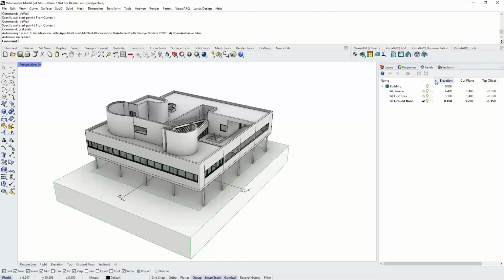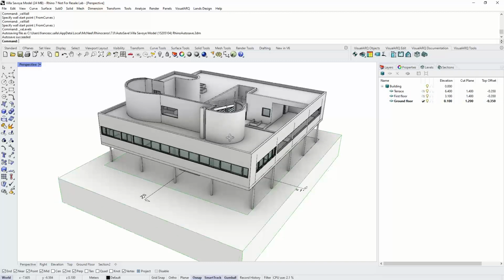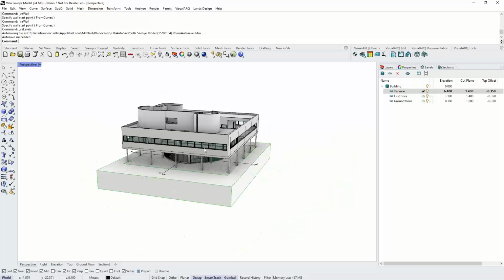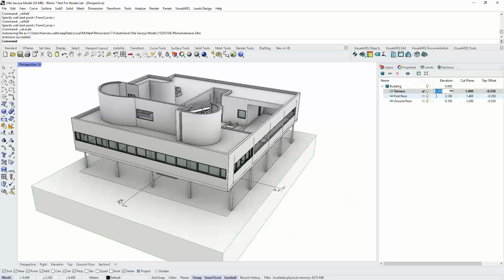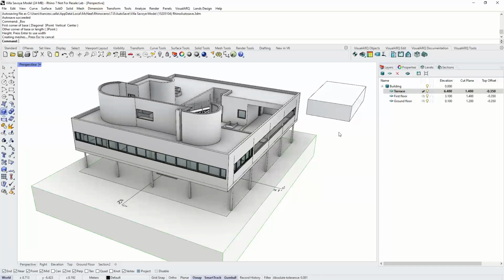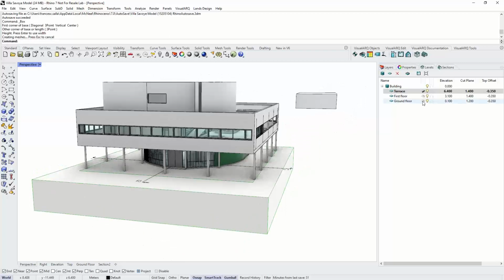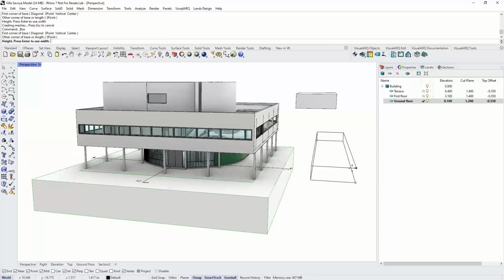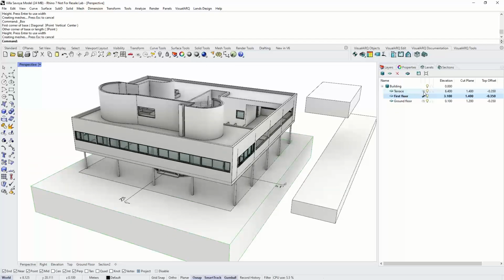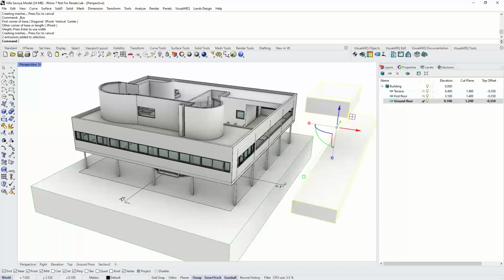And we have seen already how it works, but just to check it again in this last demo. In this project, we've got 3 levels. And basically from here, we can very quickly change the position of the construction plane, okay, that is located in that elevation. That means that if I draw anything now, this will be generated in that first floor elevation. But if I switch to the ground floor, now everything will be created on that level. Okay. It makes it very easy to switch from one elevation to another.